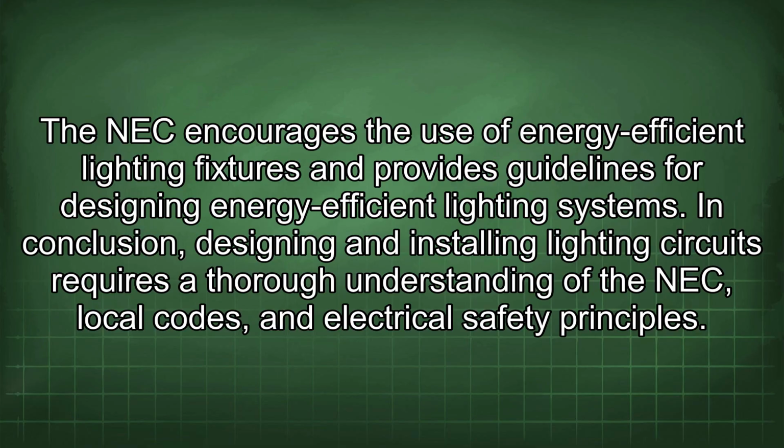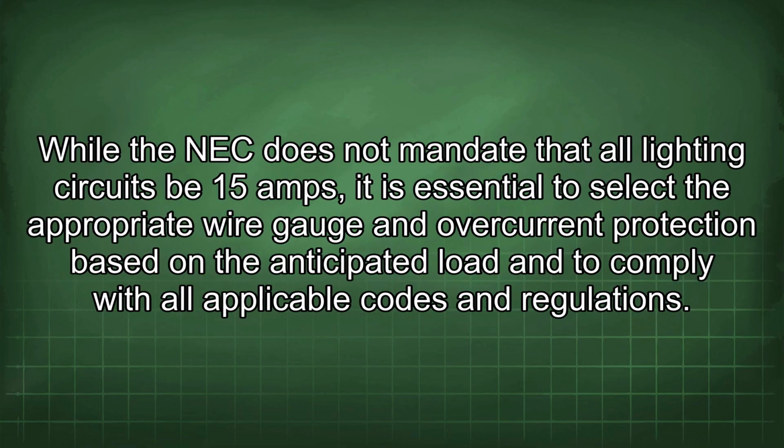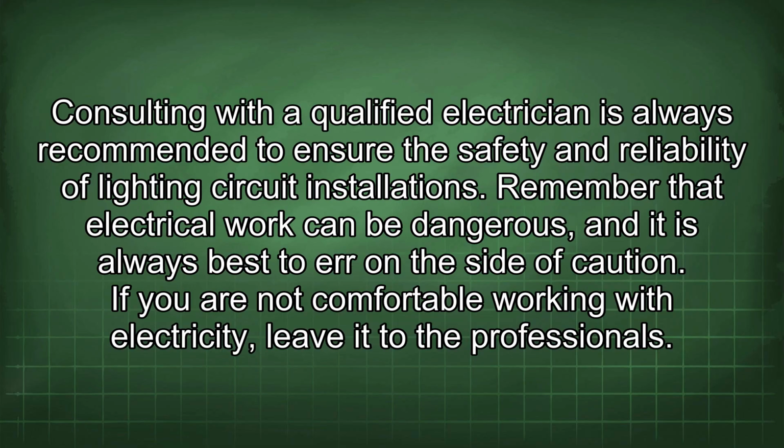In conclusion, designing and installing lighting circuits requires a thorough understanding of the NEC, local codes, and electrical safety principles. While the NEC does not mandate that all lighting circuits be 15 amps, it is essential to select the appropriate wire gauge and overcurrent protection based on the anticipated load and to comply with all applicable codes and regulations. Consulting with a qualified electrician is always recommended to ensure the safety and reliability of lighting circuit installations.